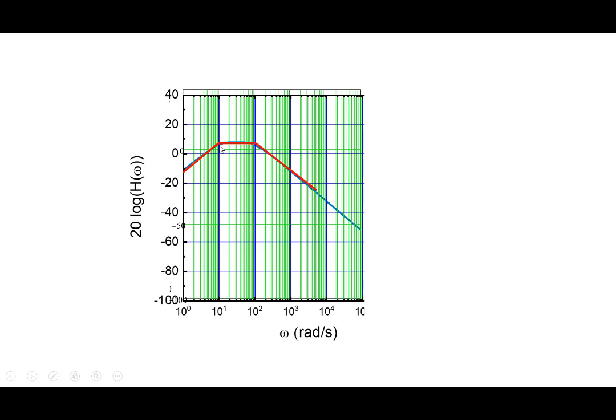In this case, we can see that it's attenuating lower frequencies, lower and lower. I've not gone below this, so lower frequencies are getting attenuated. Higher frequencies are also getting attenuated. In between, there's a band of frequencies which is passing reasonably well through my circuit here.